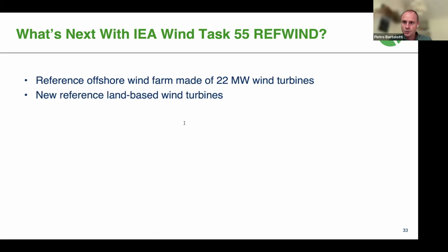Then I think there is a question for you about the natural frequencies of the turbine. Is there any consideration of the coupled tower eigenfrequency and 3P separation in the optimization process? I think no, we didn't. I think we just used the same floating tower, and that natural frequency drifts up towards the 3P, and I think that it's a little bit too close to 3P for our liking. And we've gotten a lot of very strong feedback about whether we should use a soft stiff or a stiff platform, and there's still not a lot of consensus. So we have a soft stiff platform here.